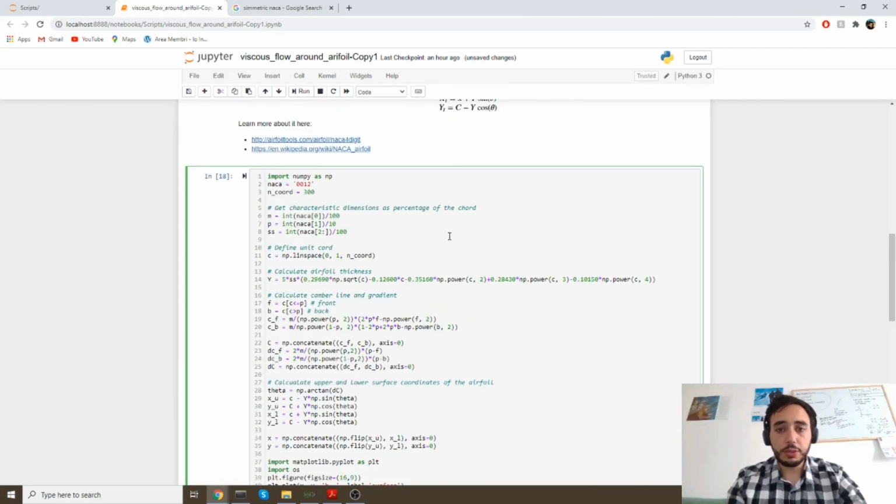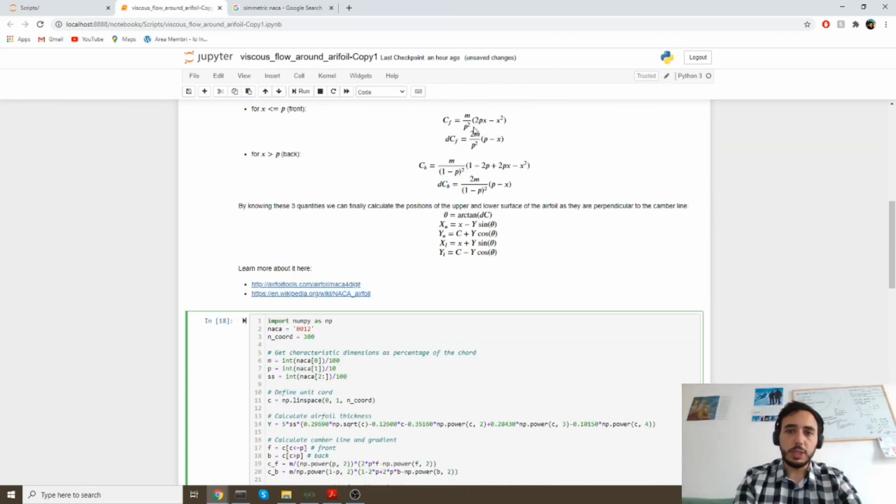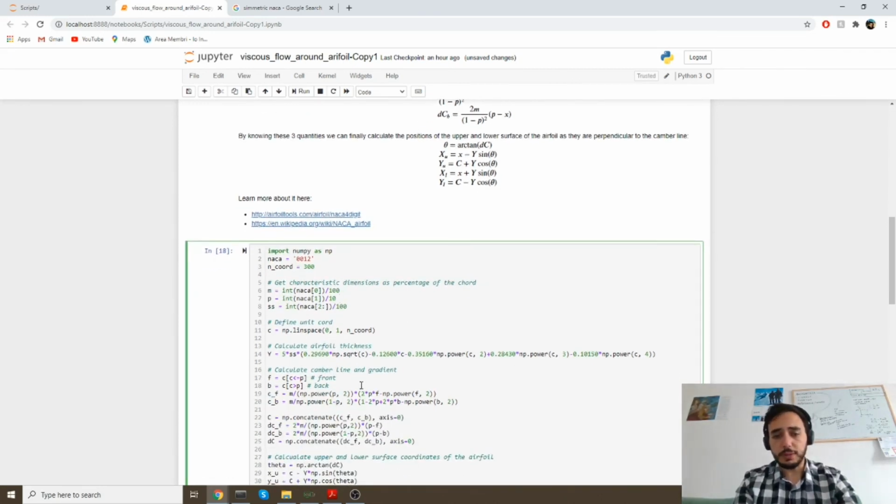So what I would like to show you now is one last thing before we end this video and move on to the next part, where we're going to improve this code a bit more using methods and classes and so on. It's the case where we have the NACA 0012, and the problem with this NACA is that the second digit is 0, which means that we may have a division by 0, which obviously we don't like. We cannot divide by 0. Therefore, we can use a final line of code to add a very, very small number, the smallest possible number that the computer can use, which is not 0.